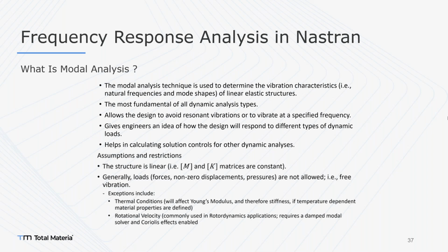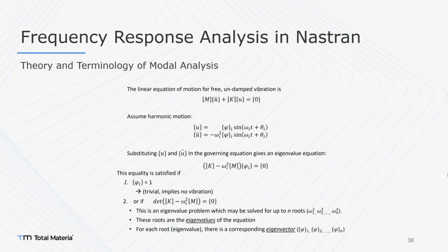Modal analysis, by the way, is really good when you have an assembly for static analysis. If you have an unconverged situation and you don't understand what is going on, you can go for a modal analysis. Maybe you have unconstrained sections, which give a rigid body motion. Correct me if I'm wrong, Erdi. So it is a really good way to check your static analysis as well as dynamic analysis. Do you have anything to add, Erdi?